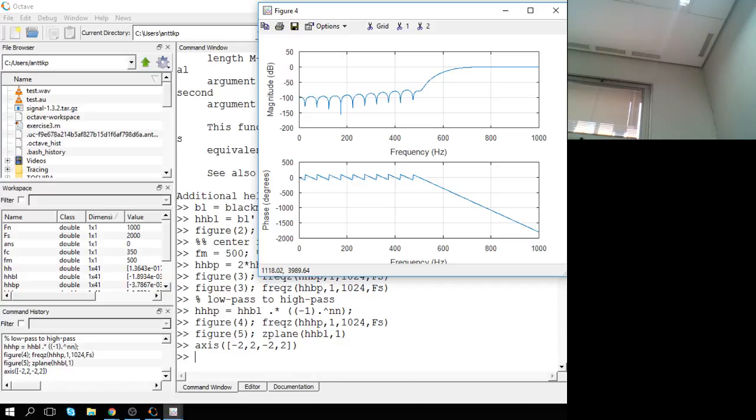There, you don't need to make the different bands, especially on the FIR filters. You don't need to band filter separately. You can just add the coefficients and have one filter with varying coefficients. Okay, good.